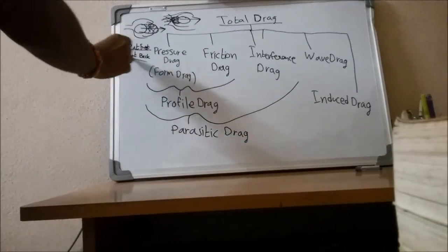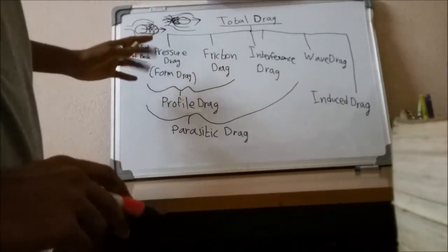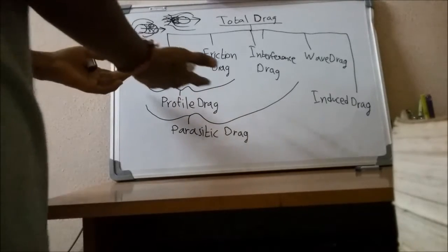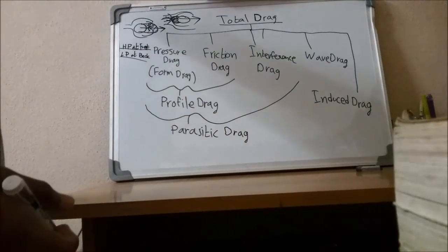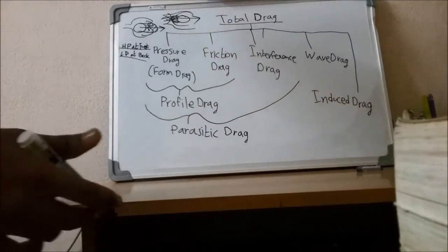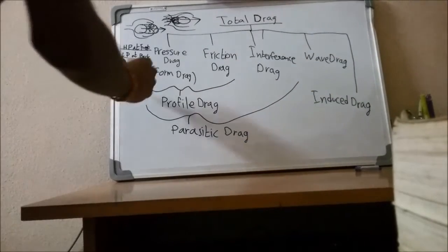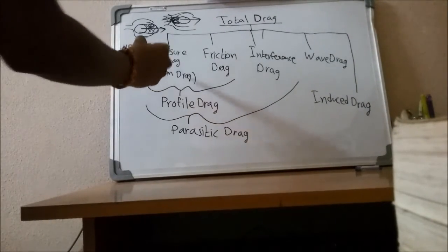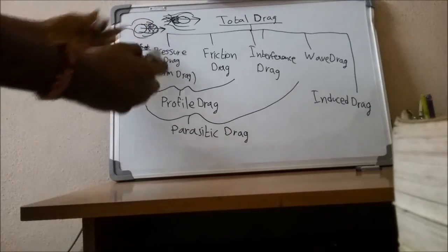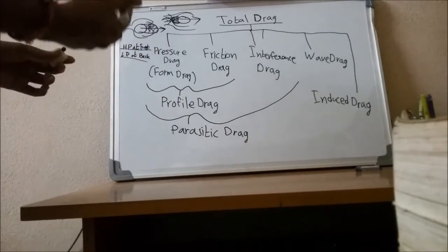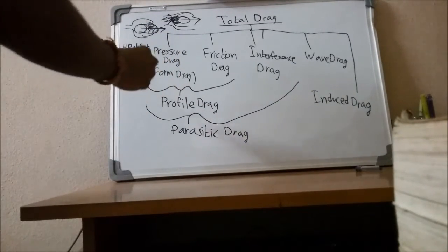That is known as low pressure. And another one in this pressure drag, also known as form drag, is that flow separation around the object can also cause drag. Flow separation generally occurs at the back portion as well as at some critical shapes of the object.